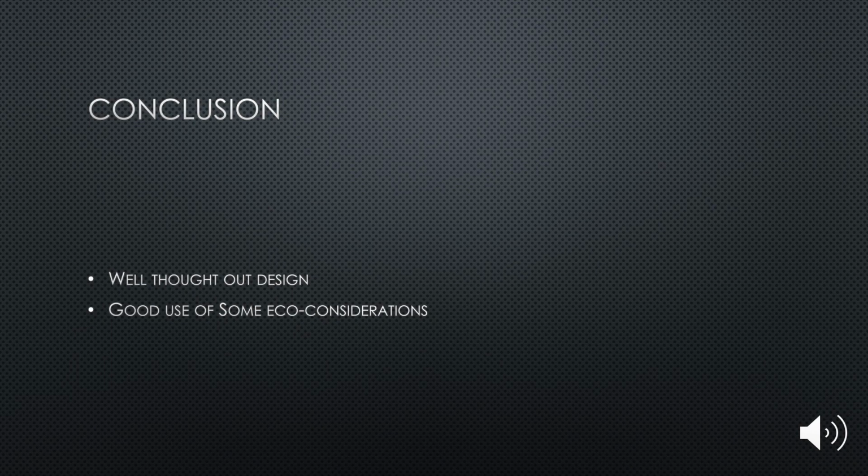Further reducing torsion. To reduce any more torsional effects due to the warped columns, core lintels were placed above main doors and are composite with steel, rebar and concrete, as you can see from the image on the slide.